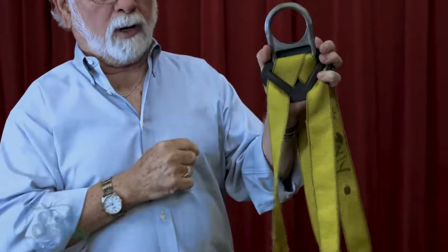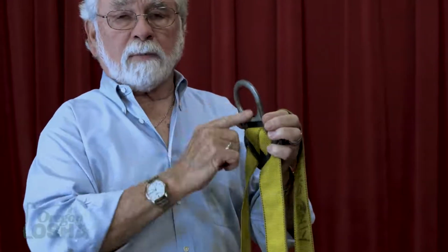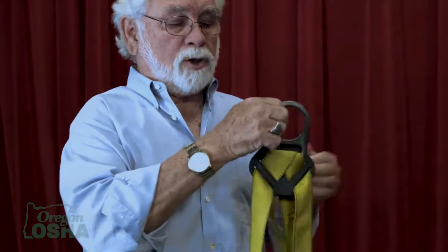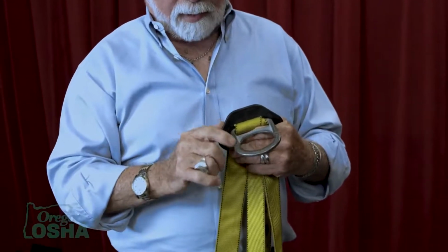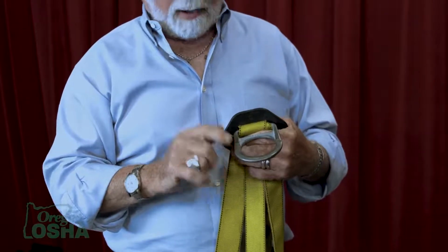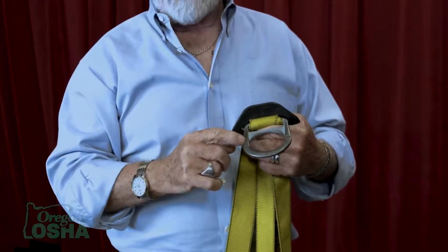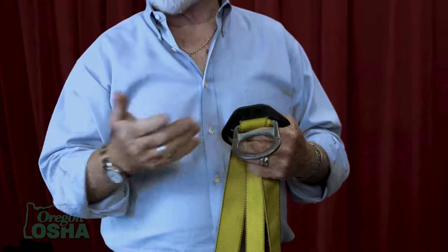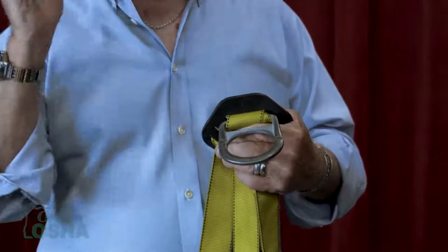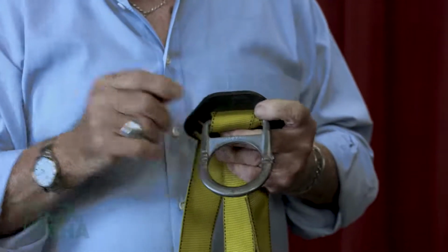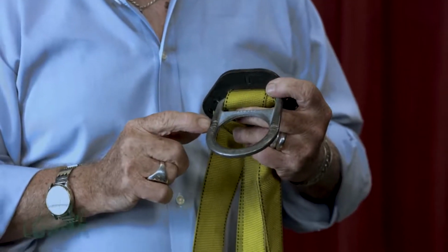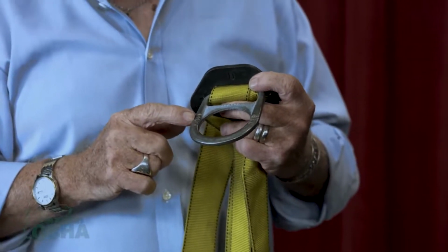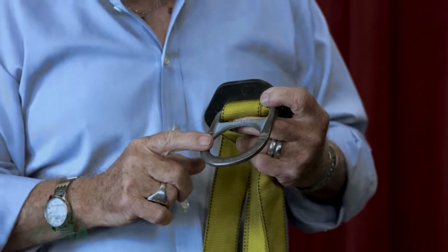We want to look at the D-ring, make sure it's round, feel it to make sure there are no nicks in it, and check to make sure there are no worn spots here. This is an actual reproduction of a harness that came out of the initial wind towers in Oregon, because when those towers were formed, the weldment to the inside had little sharp protrusions. And the fellows that were working in there would lean back on the tower and it would puncture their bodies and they would bleed. That's an accident.